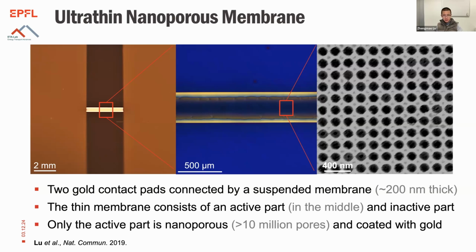During the experiment, we route the liquid to underneath the membrane and use wicking for the liquid to enter the pores spontaneously through capillary action. We pass current through the metal layer to provide heating to induce evaporation, and also to maintain a steady state and measure the temperature with its resistance. So roughly, that's how the device operates.